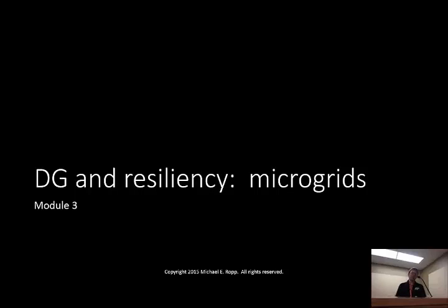And we've all heard this term microgrid. It's become the buzzword of the week in our industry. For us, what we're going to say is, basically a microgrid is an island that we can island intentionally. It's as simple as that. Microgrids, by definition, have a grid tie. If it's like a standalone system that is always off grid, we just call that a low inertia system. Microgrids generally are low inertia, but not all low inertia systems are microgrids.